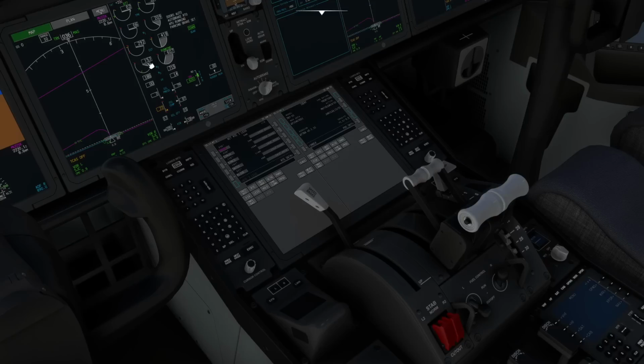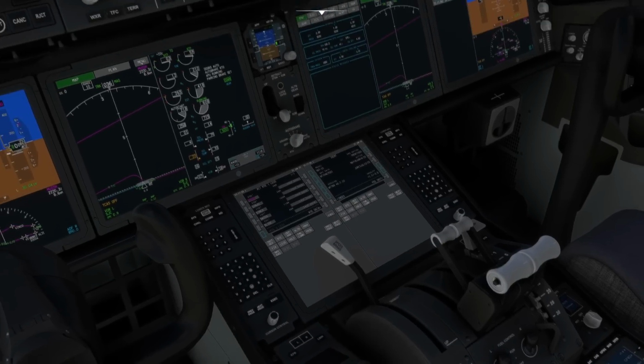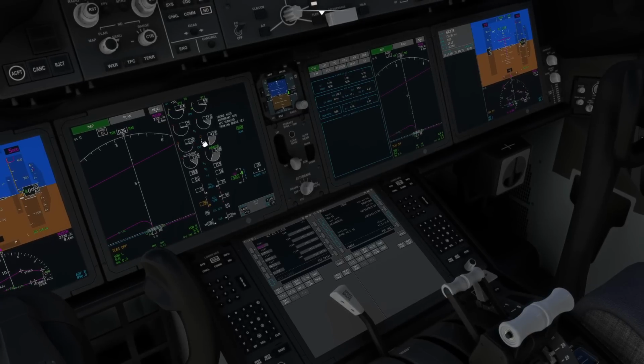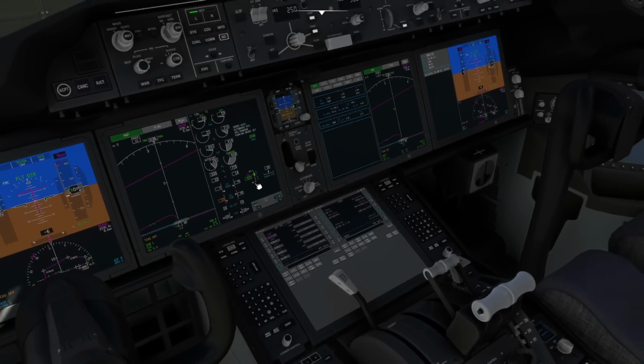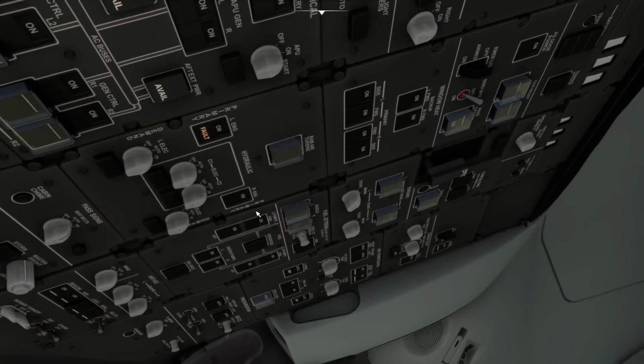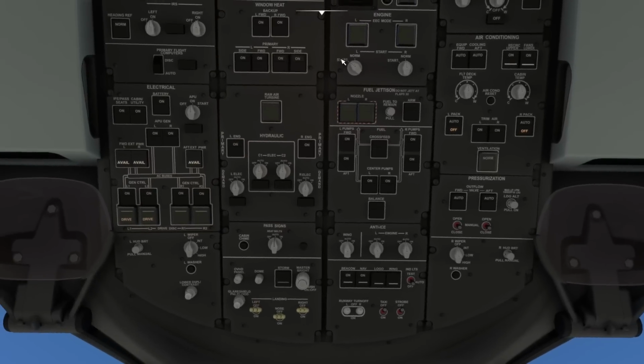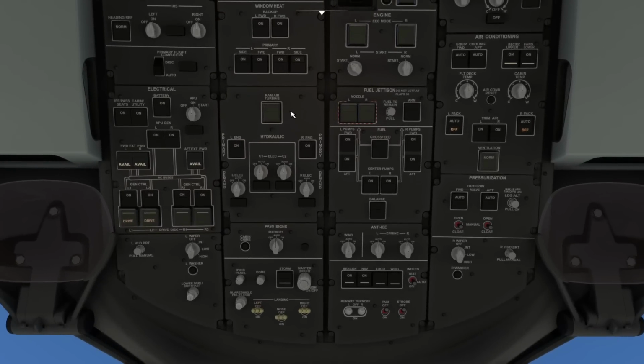So it's gone 14, 15, 16, 17, 18, 19, 20, advance the lever, it continues on past, it says auto start. The exhaust gas temperature will start rising, there it goes, N1 number is increasing, that's the turbofan, and then you'll notice, let's do it from this view, the start mode will go back to norm.